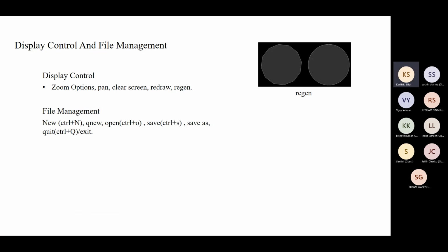When do you decide you have to refresh in AutoCAD? This is your circle, a normal circle, but sometimes your circle will be displayed like this in AutoCAD. When you are working continuously or the file size is very big, sometimes the circle looks like this, or in a deformed shape. Then you have to press RE, that is regen. Then your circle will appear normal after that.